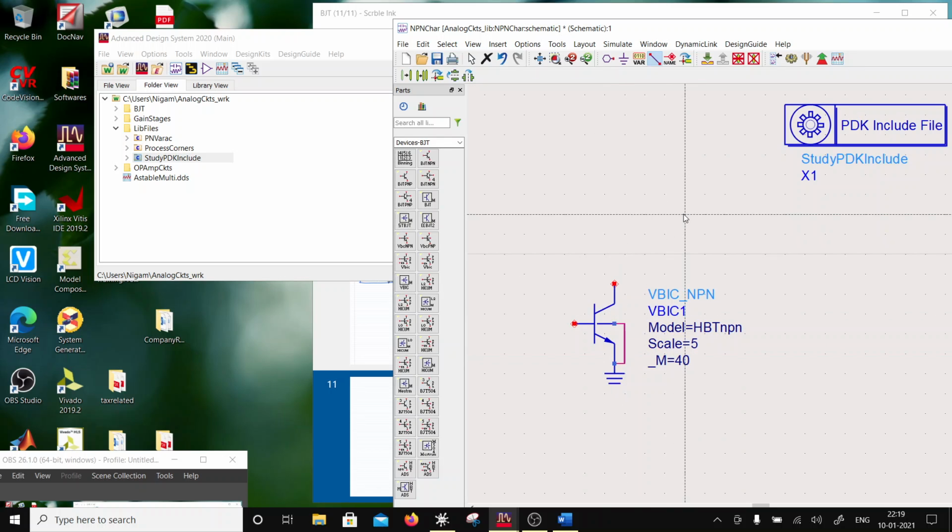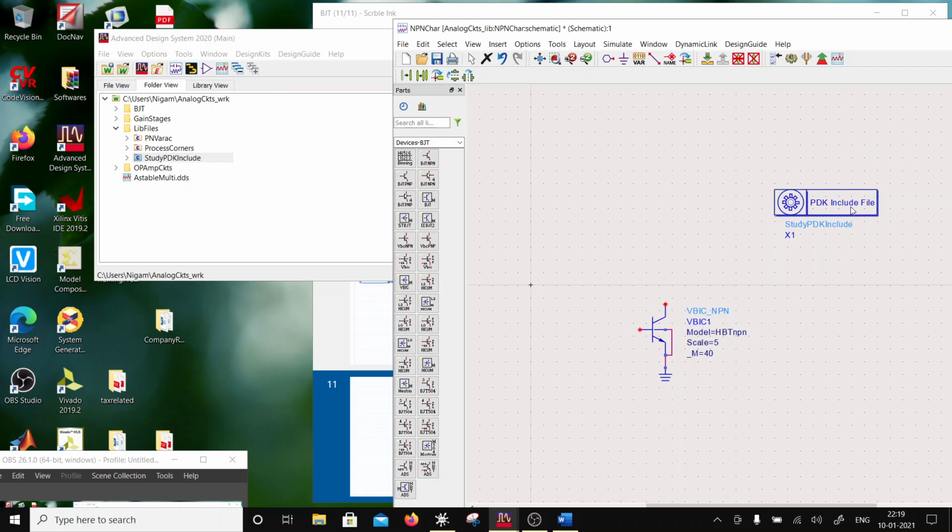Okay, the way an analog designer biases a transistor is slightly different from the way the RF designer biases a transistor. An RF designer is more concerned about instability or oscillations on a big device. So this is not a big device, but usually they try to place the device in an impedance of 50 ohms when they do the DC parameters, right? This is because the expectation is that the center of the Smith chart is going to be the most stable portion, while the periphery is going to be the least stable.